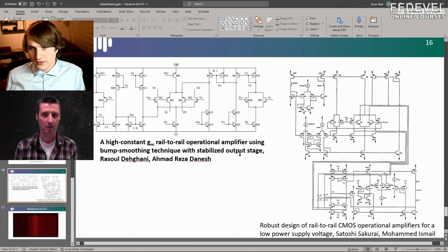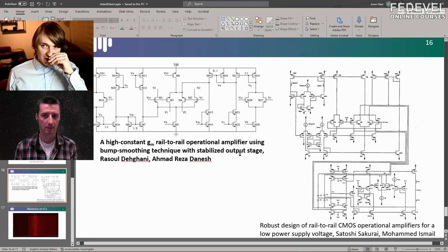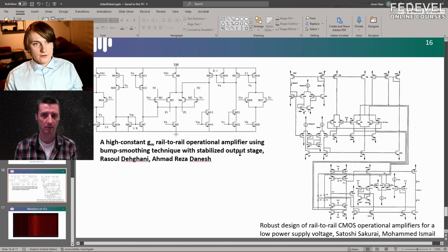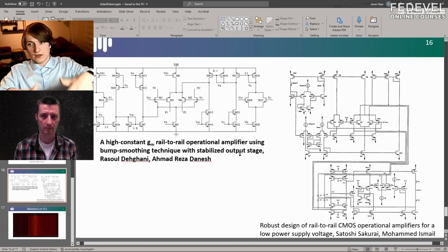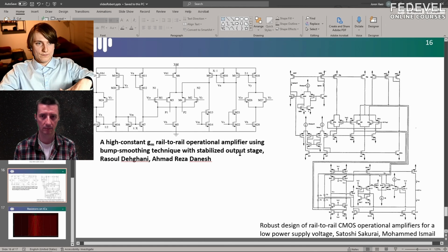That is one possibility. So that's something that is done. They might have special additional bond pads that are not connected to the actual frame, but when they do the assembly of the chips, they have a probe card that lands, has maybe 1,000 pins, and then can measure this chip in big automated test systems to measure that resistance and then program in the value.